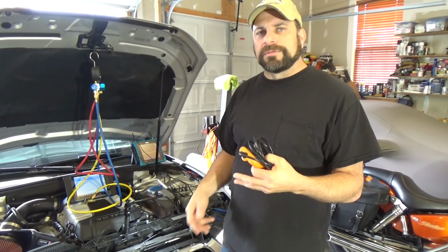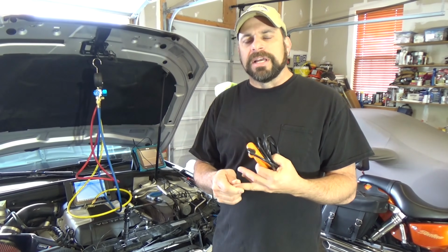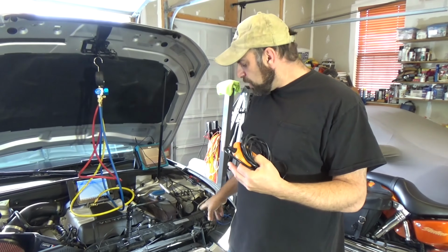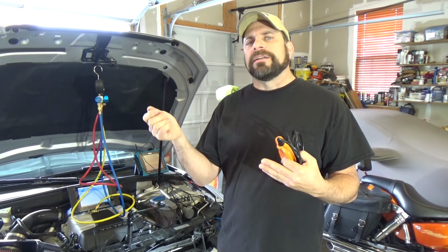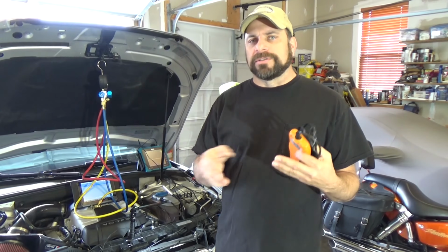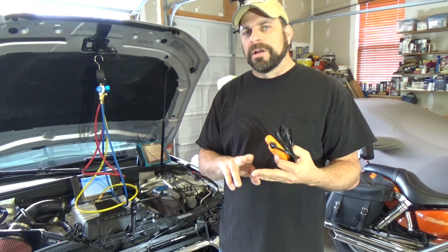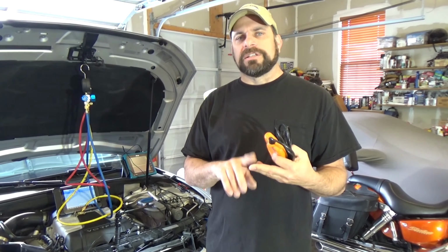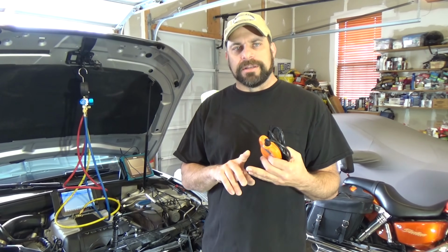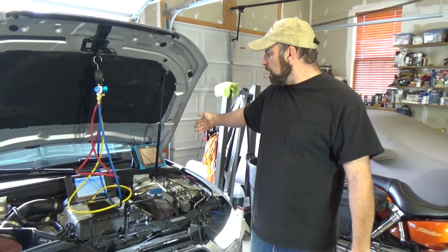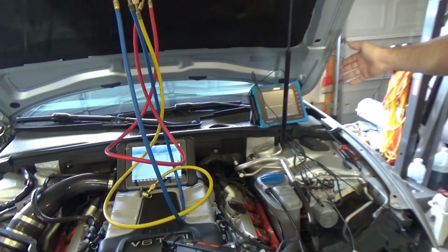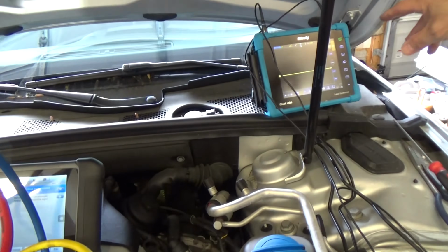Well, the issue with this particular car, or not issue, but the technology, is that the signal wire, which I'll show you down here in a second, is a data line. So this data line sends packets. I believe it's the LIN bus; there's CAN bus and LIN bus. LIN bus is a little bit slower. This is the system that would run your power seats, power windows. I'm told on the Euro cars now that even the electric water pumps and the electric thermostats are all run with LIN bus. So it's data packets, and I don't know if you can see right back here is our oscilloscope, and in a couple minutes we'll hook that up and I'll show you how you can see that.